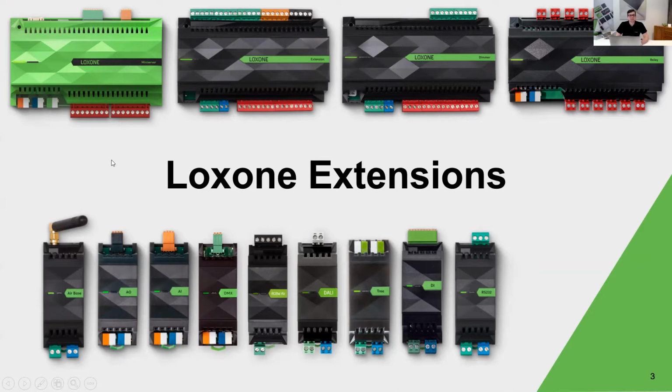These relays are rated to 10 amps. We might need 16 amp relays for certain high load circuits. We might need mains dimmed circuits to control. We might need to do RS-232, 485, many other potential protocols and communications. And this is what extensions are for. With extensions, we can expand our system beyond just a mini server to cover as many different things that we need to talk to as possible.